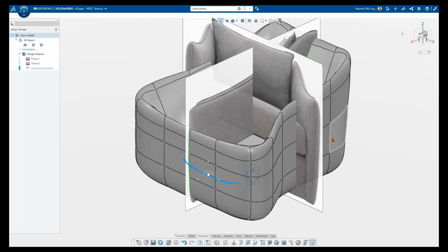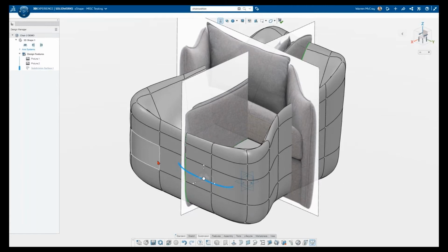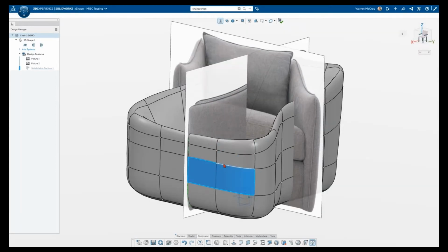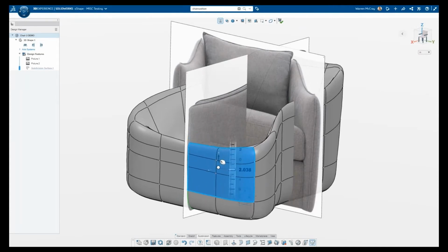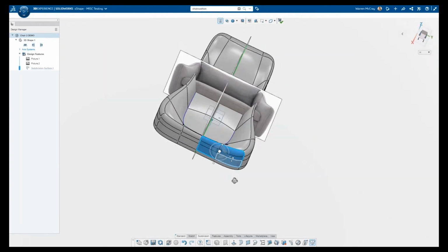So I decided, let's look at another area here. Okay, so let me try moving these faces again. This time I'm going to try picking more than one. There we go, and I'll grab it and pull. So now I'm pulling all three faces at the same time. So instead of it just moving the first face, I actually am moving all three faces simultaneously.